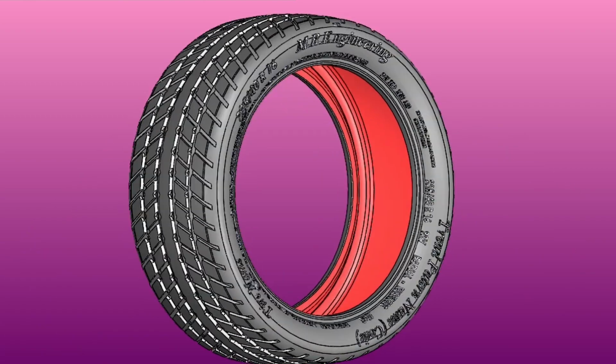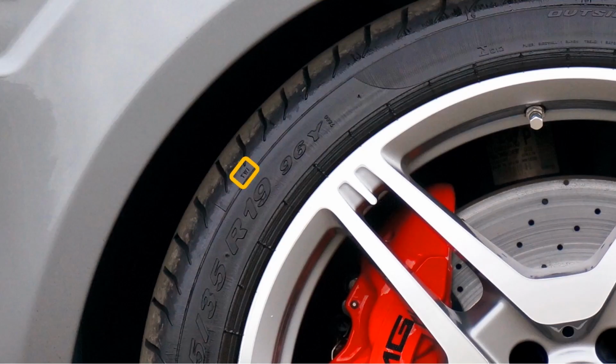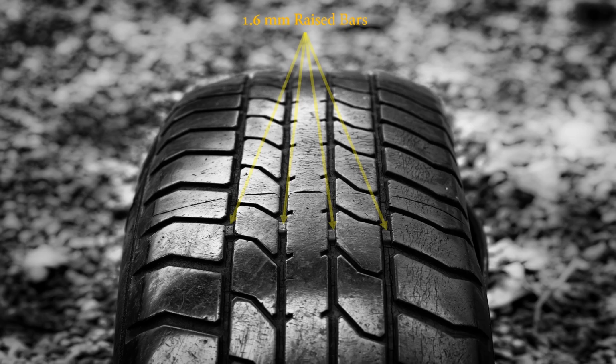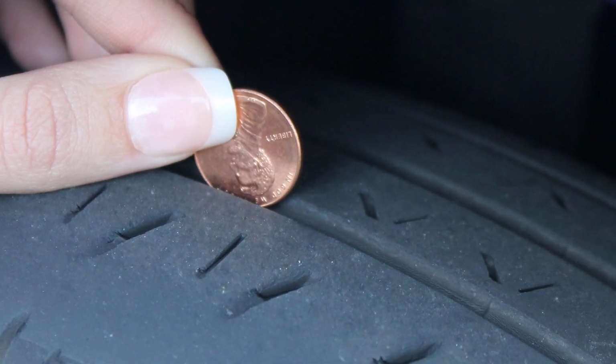Near the tread, you can find a marking as TWI or a triangle that is an indication of where tread wear indicators are placed on the tread pattern. And these tread wear indicators are 1/16 of an inch or 1.6 millimeter raised bars, and when the tread surface reaches these bars, the tire needs to be changed according to the regulations.